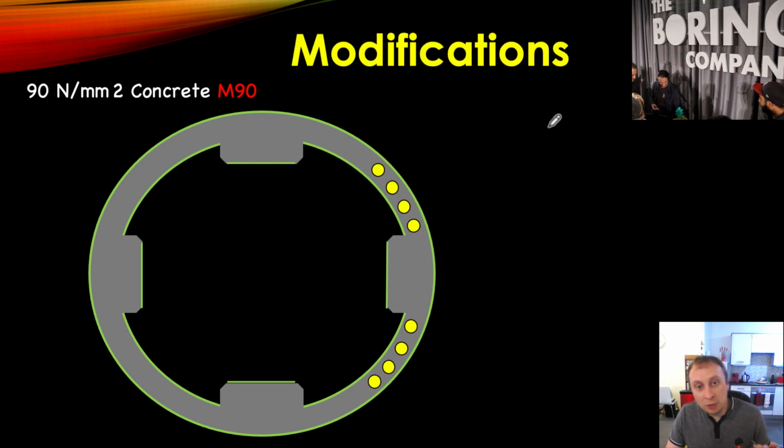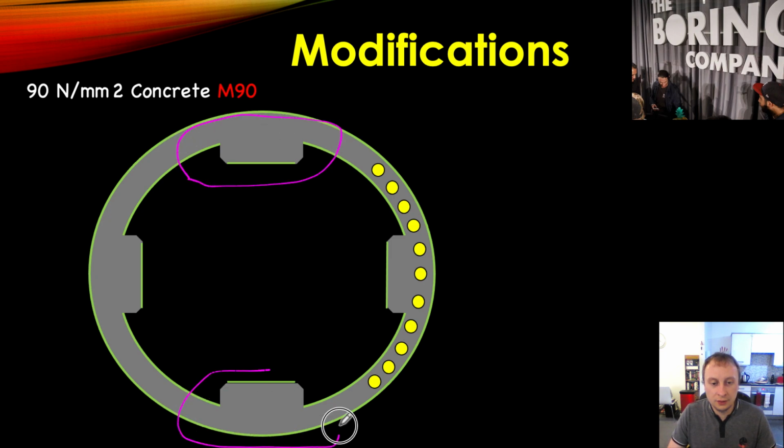We're going off point here a little bit, but as you can see here, this is where our thrust cylinders, or our jacks, actually push themselves off the segments. As you can see, I've got 4 jacks here. Now, normally it would look like this. So you'd have it like this, and then you'd have it on the other side here as well. So you'd have some on this side. And then you'd push off in 2 goes, basically. So you'd be assembling up here, and then up here, and whilst you were thrusting off on the left and right side of our illustration here.